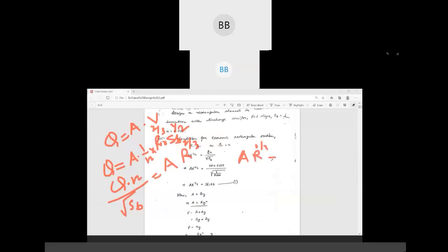Find out how much you got, because the discharge is known to you, that is 20 meter cube per second, n value is given, and slope is also given. So what we did, all the known values we bring in the left hand side, to find out the right hand side. That is, area is not given, R is also not given, so these two terms are not known to us, so that is why we bring all the known parts to one side and we find out this value. See, you are getting the same value or not? 16.43.